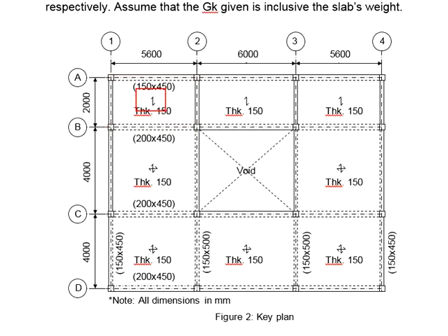One-way slab happens when the Ly is more than 2 times greater than the Lx. When the slab is considered one-way, that means you're going to expect bending moment diagram only at the shorter span.